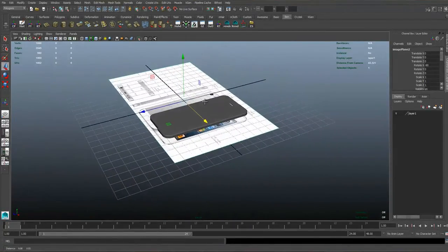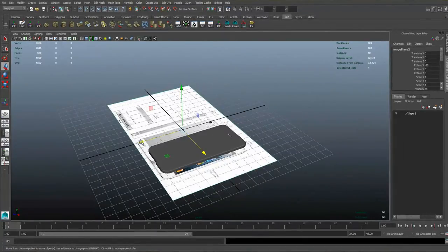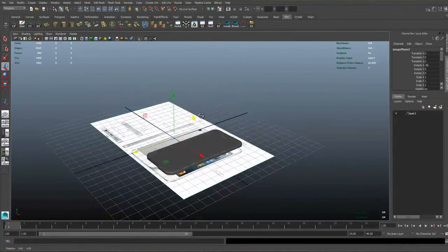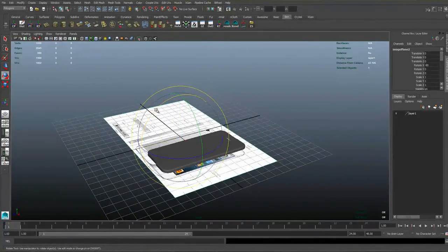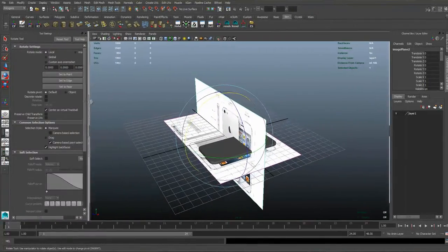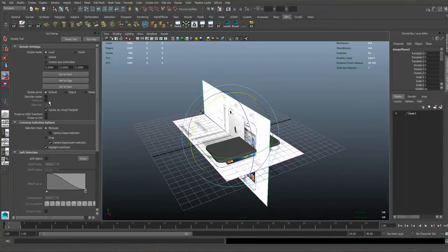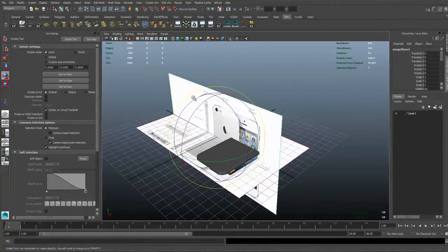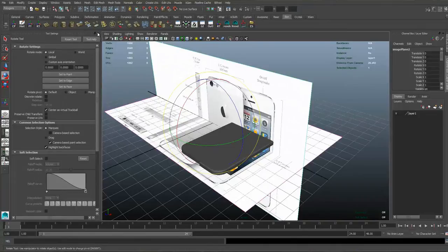I've actually just pressed Control D on the geometry, and I can move it about, but let's just hit E, and if you hold down J for rotating, I've set my rotate to 45 degree increments. If you need to change this, if you're at uni and the computer's reset every week, you'll just need to double click on your rotate option, check discrete rotate, type in 45 or 90. I like 45, and uncheck it, and then uncheck it again so it goes grey. It was probably 15 beforehand, and then close it down.